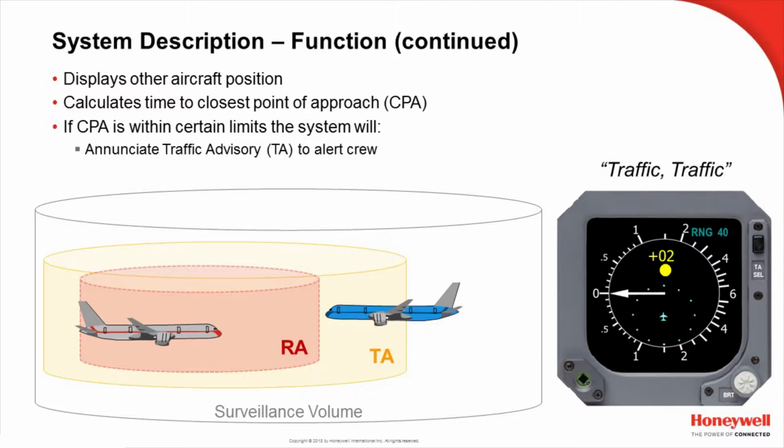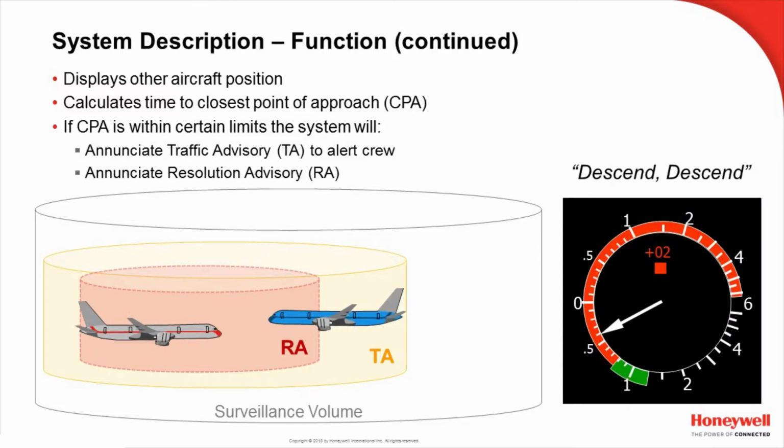If the situation continues to get worse and the aircraft closure rate continues to be within unacceptable boundaries, we may then generate a TCAS resolution advisory. This will change the color of the TCAS symbol to a red square, but it will also give us a guidance command, a vertical guidance command, so that we can achieve a safe separation. It could be a climb, it could be descend, or possibly even maintaining our current altitude. This would also be accompanied with an audio alert, which would complement the vertical maneuver.